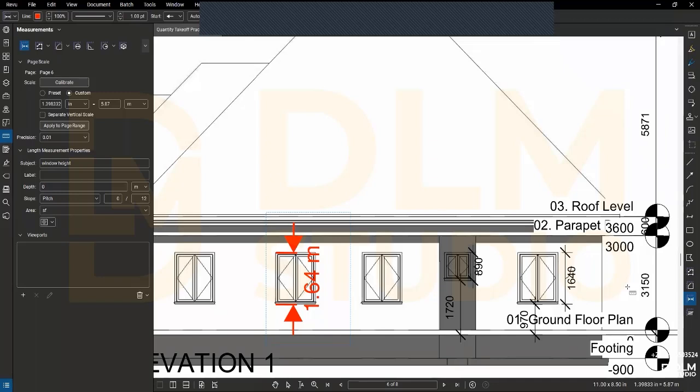Now in description, you describe to detail: 1 to 4 mix concrete with 20 mm aggregate, filled with so and so. Describe to detail. Anybody who picks up your document will be like, oh okay, they can easily trace that description to wherever it is, either on site, and you know where that cost is attached to. When we describe vaguely, concrete in foundation, what's the specification of that concrete in foundation?